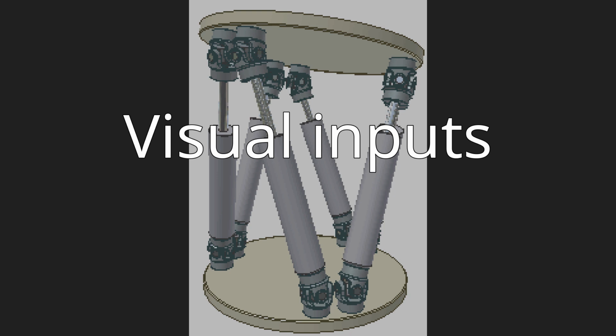As discussed above, for example, if the occupant commands the vehicle to roll to the left, the visual displays must also roll by the same magnitude and at the same rate. Simultaneously, the cab tilts the occupant to imitate the motion. The occupant's proprioceptors and vestibular system sense this motion. The motion and change in the visual inputs must align well enough such that any discrepancy is below the occupant's threshold to detect the differences in motion.